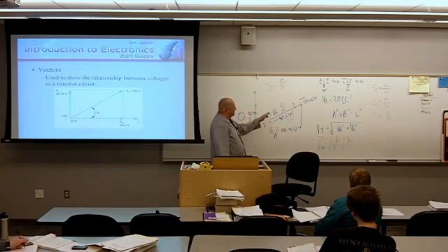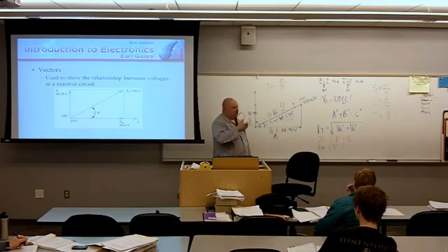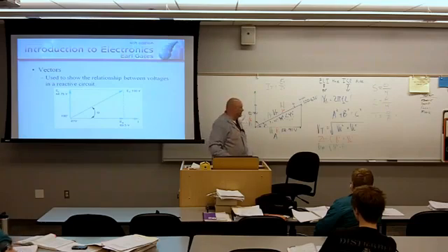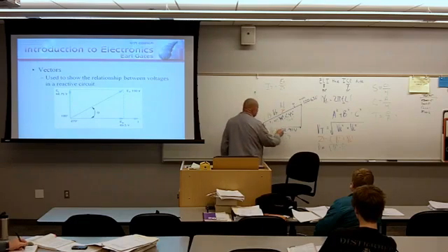And where would I plot that out on my vectorial plot? Down the bottom? On the same vector as what? Resistance. Absolutely. Why? Because resistance is in phase with current. And total current is total current. Whatever's happening at one point is happening at the other point. There's no phase shift of current in the circuit, from any point in a series circuit. So IT is going to get plotted out on this vector.